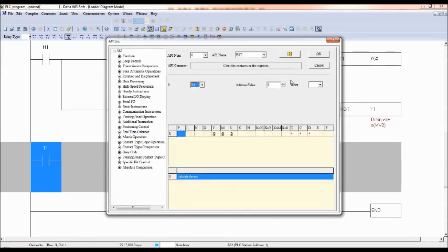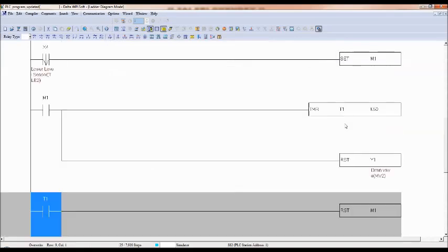See why this is a reset? By using the falling edge, we are storing the data. That means when we are switching on M1, one more time it has to detect the empty tank. So at the time filling starts, we are also resetting M1 so that it can detect the empty tank again. Okay,